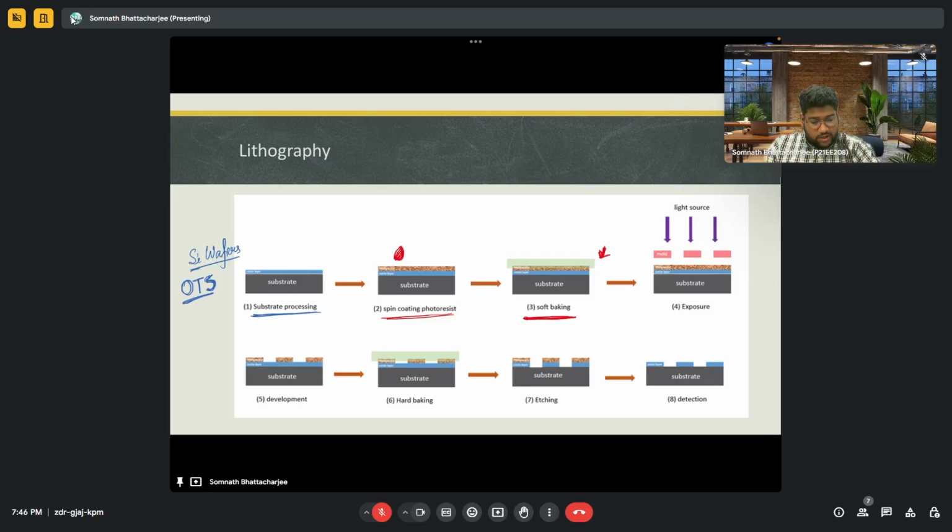After that, we'll put a mask that is called the photo mask, or you can say the photolithography mask as well. So there will be a light source. Okay, so this is like they have told as a mold, or it is also called a mask, photolithography mask. Yeah. So then the light source is lined. It can be a UV source as well. In most of the cases, that is the UV lithography.